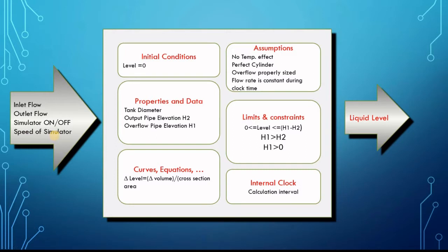If you said that this tank calculation is made every 1 second, but you want to run the whole simulator at a speed of 2, that means you will run it every half a second, not 1 second. If you multiply the speed by 10, you divide your timer by 10, that means you have to do the execution every 100 milliseconds. That's to speed up your simulator and see the results of 10 minutes in 1 minute. Of course, you don't need to have all of these, but that's the general idea.